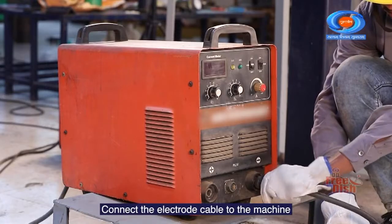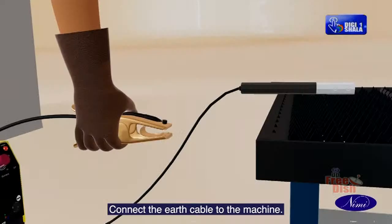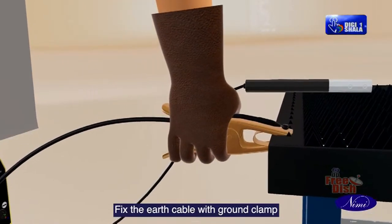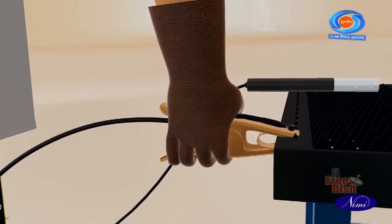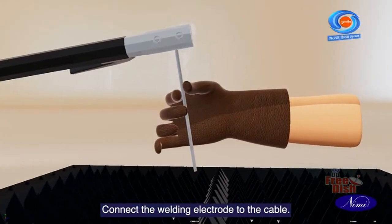Connect the electrode cable to the machine. Connect the earth cable to the machine. Fix the earth cable with ground clamp and clamp it to the welding table. Connect the welding electrode to the cable.